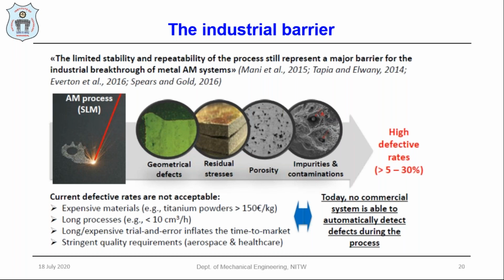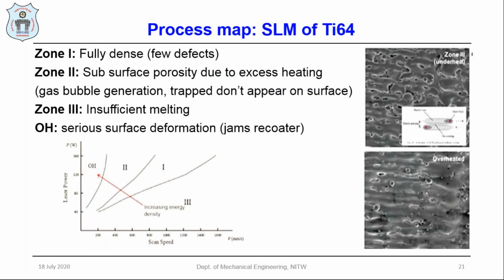That is the repeatability, or the comparison from process to process, which is a very challenging issue in these metallic components. And also the online monitoring system: it has to automatically detect the defects when fabrication is going to occur. Those are the challenging issues in additive manufacturing systems.